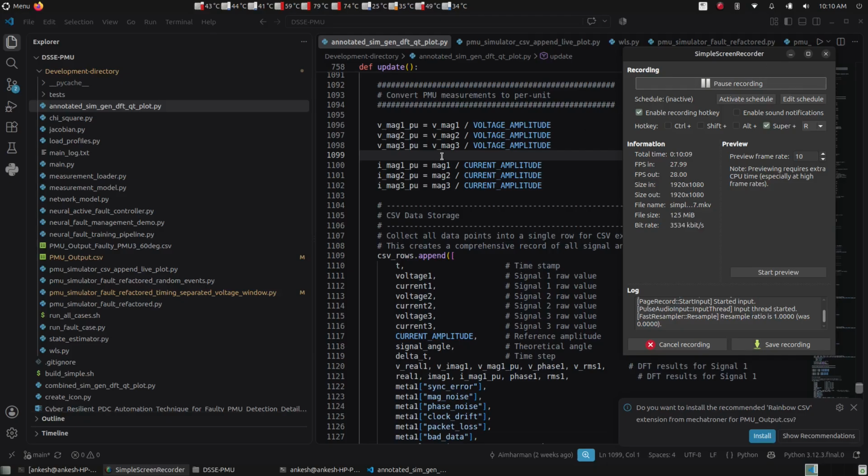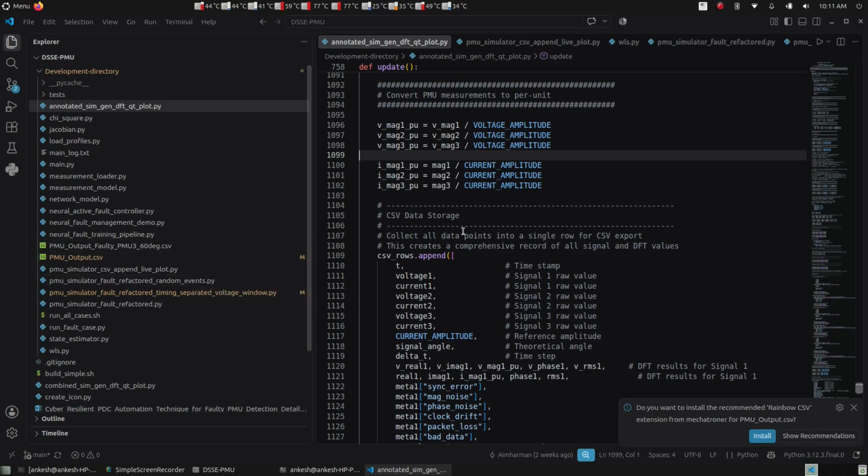Next we will go on to the project structure, and I will walk you through the PMU detection side. This was the generator, the output which we are getting from a phasor measurement unit. Now this data is ported to a phasor data concentrator, where the information being sent by the PMU gets evaluated. This was our actual project. In the absence of actual three-phase supply data from an actual PMU, I had to make a PMU simulator that generates the dataset for me, and only once the PMU simulator was made could I make a fault detector for it. So now we'll move on to the fault detection side of my project.